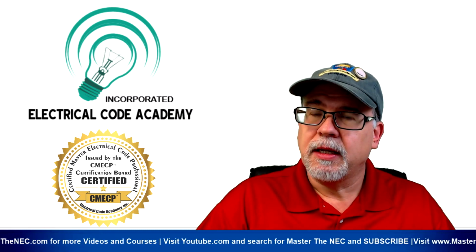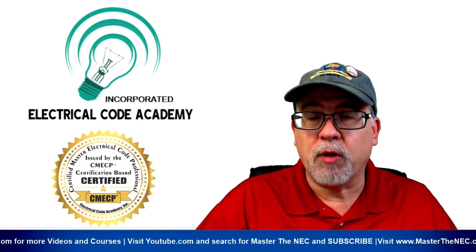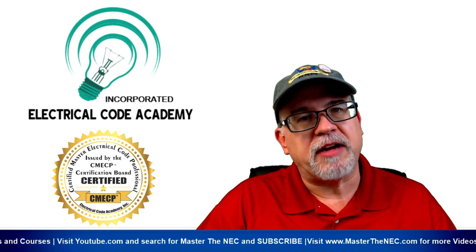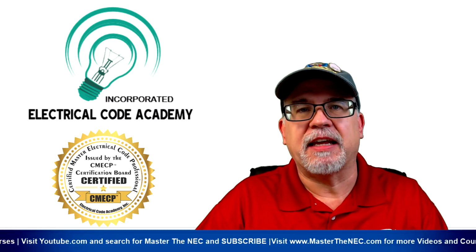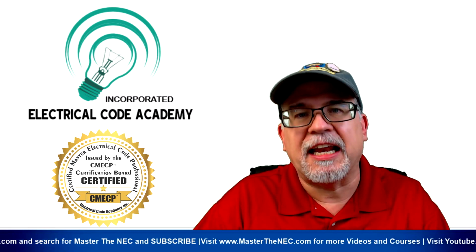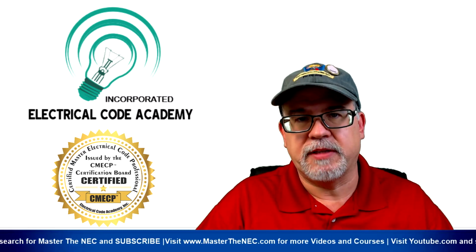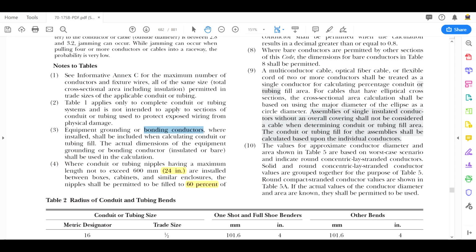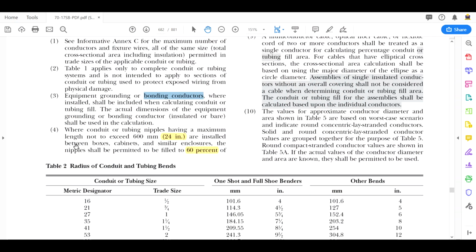If it's a bare equipment grounding or bonding conductor, then you go to Chapter 9, Table 8, because that gives the approximate area of those stranded or solid conductors. But you definitely have to account for them. They do take up space.